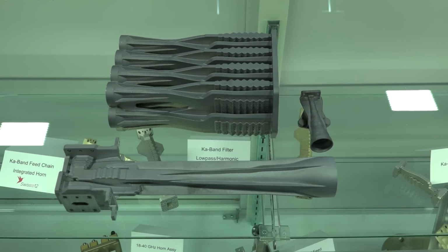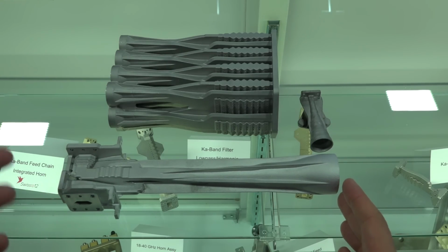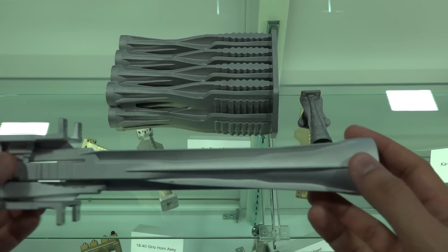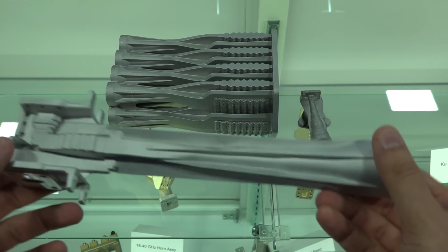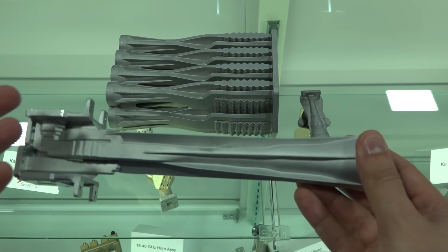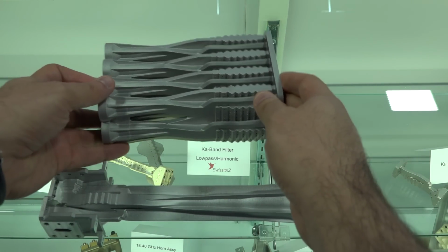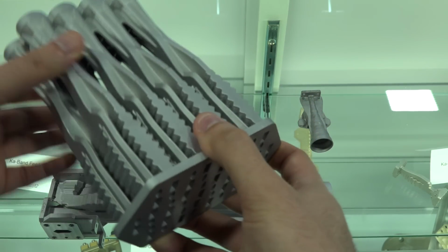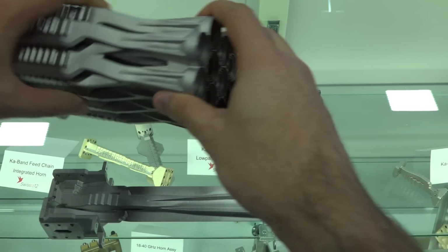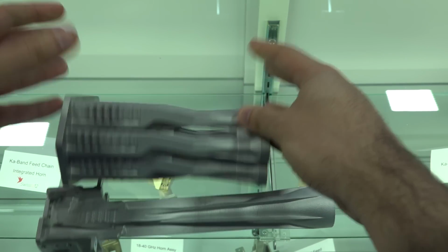So here at Swiss 212, we have a whole bunch of interesting metal printing technology used for microwave and higher frequency bands. The fundamental idea here is that if you could print metal directly from a 3D printer with a custom firmware at the feature sizes you're looking for, you can start to make what are essentially impossible features directly in one piece. So you can have filters and diplexers and transitions and waveguides, even a combination of a whole bunch of them into one flange with all the interfaces at the same time, which would be impossible to machine. This will be significantly lighter.